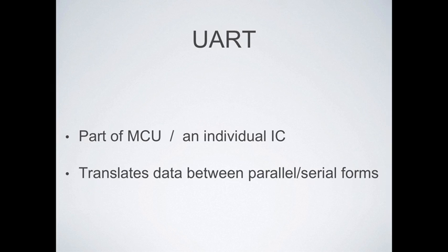UART stands for Universal Asynchronous Receiver Transmitter. UARTs do exist as standalone ICs, but they are more commonly found inside the microcontroller. So you want to check your data sheet. You can have one, none, or many UART interfaces.